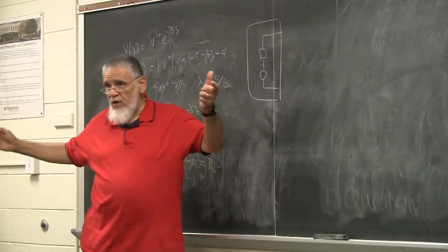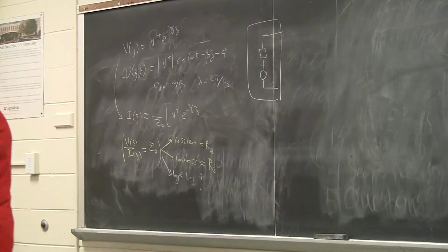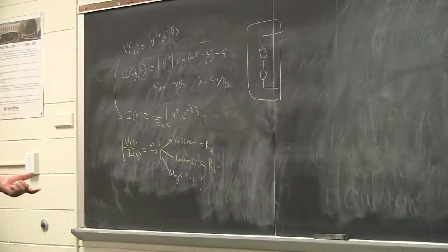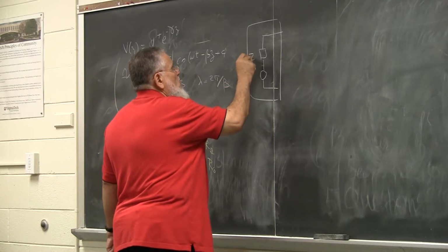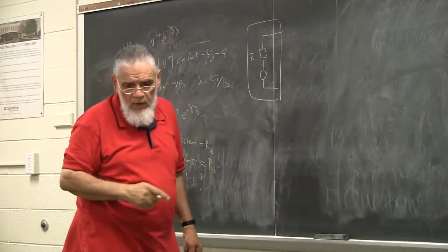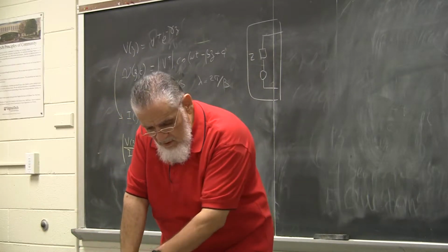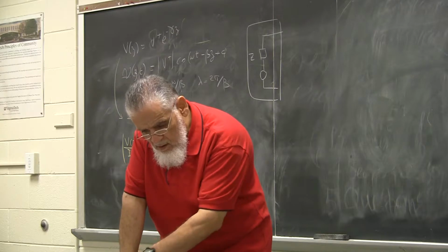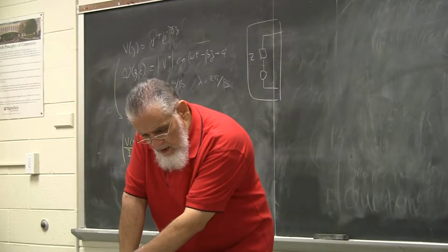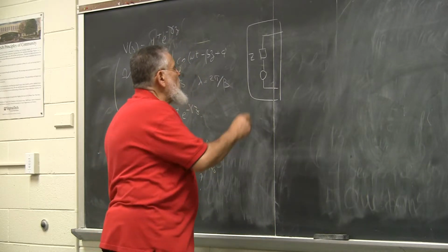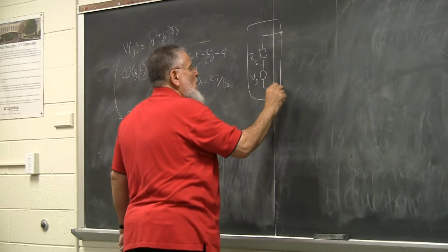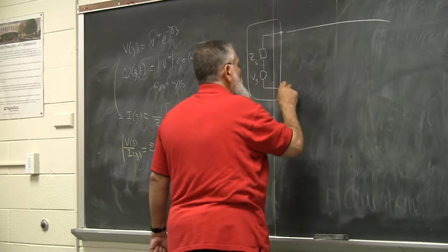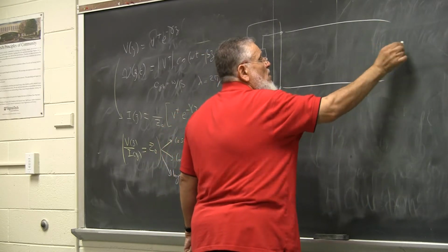The source could be a very complicated circuit, could be another transmission line, could be whatever, and I simplify it by a Thevenin equivalent, all right? A Z Thevenin and a V Thevenin. So we call the Z of the source end. What notation do I use? Do I use sub S? Yes, I use sub S. Z sub S of the source and V sub S of the source. And here's my line, which I assume has nothing coming from the other end.